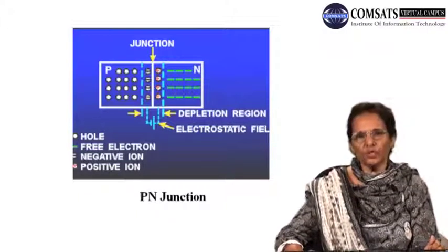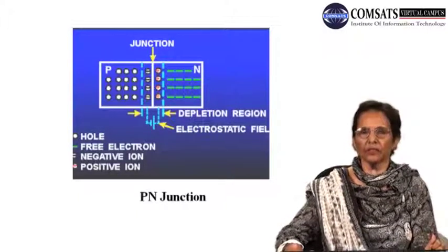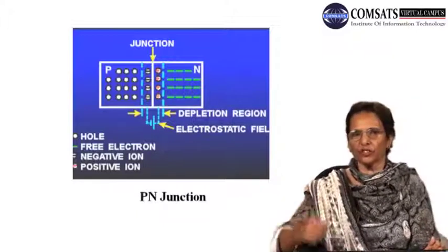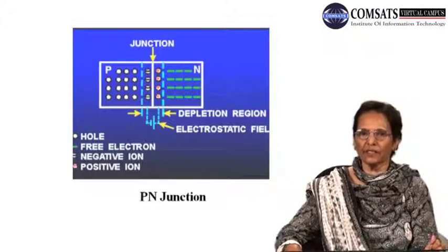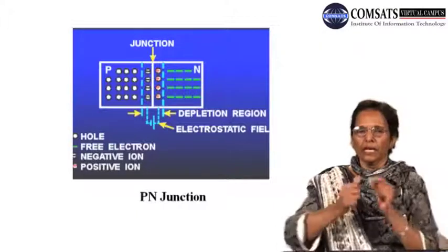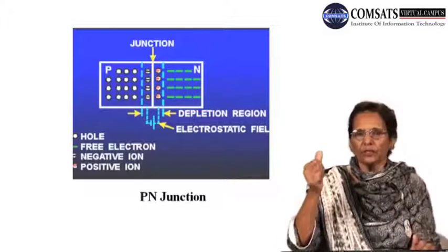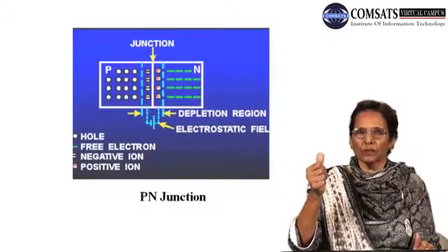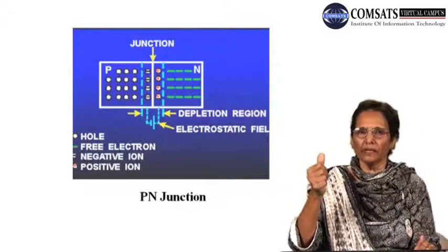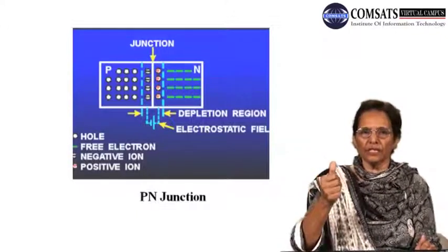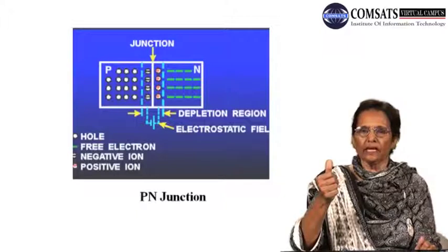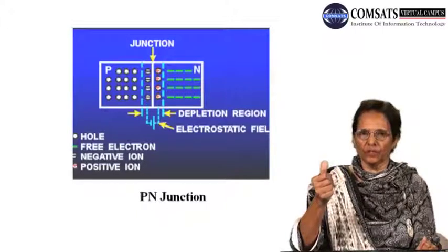A junction, as you see in this slide, is characterized by what we termed the junction characteristics or PN junction parameters. Namely, due to the diffusion of the majority carriers, holes from P to N and electrons from N to P, as we already discussed in detail, we leave behind the uncompensated, ionized donor and acceptor layers on the respective sides of the junction.